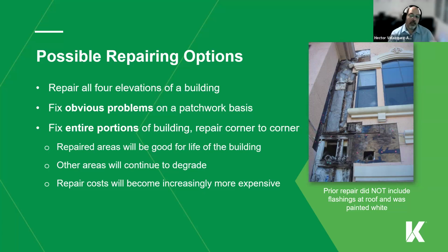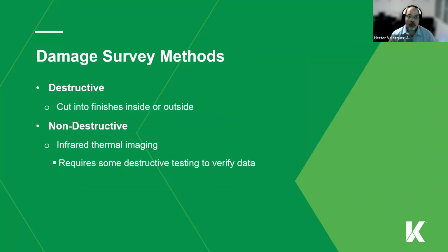The same thing applies to concrete. Today you see a crack. Well, I'm not going to fix the crack. Well, now you got stucco falling off. Well, now you got a spall. Now you got the rebar. And it's going to continue to grow. It doesn't stop. There's no such thing as rebar corrosion stopping. We control it as best as we can, but it will continue. So you should do a comprehensive repair and not a patch.